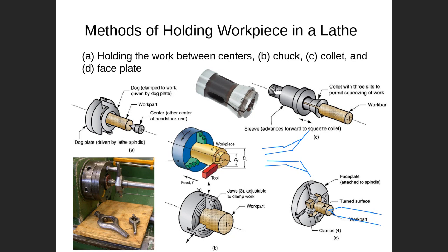And then when you release here, there is a spring system to bring this one inside, and then you clamp. Then you can clamp and unclamp by using a pneumatic system, which is the automated system. This is exactly like the mechanism you have in the pencil that you use. So this is an automated system, mainly different from the chuck and faceplate.